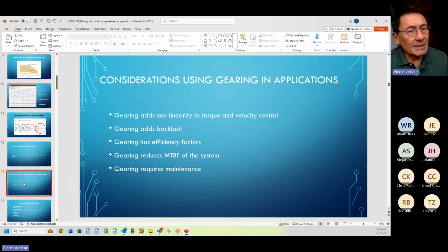And that's the case of linearity. In many cases, it doesn't. Because of the geometry of the teeth of the gearbox, etc., and backlash is another issue, it may land on 18.1 or 17.7 degrees. Therefore, it's nonlinear. It's not perfectly matched up to the input motion. That nonlinearity isn't acceptable in many applications. Does it matter in a conveyor where you're always going in one direction? It really doesn't. So a lot of these have greater or lesser importance in the applications that we're discussing.